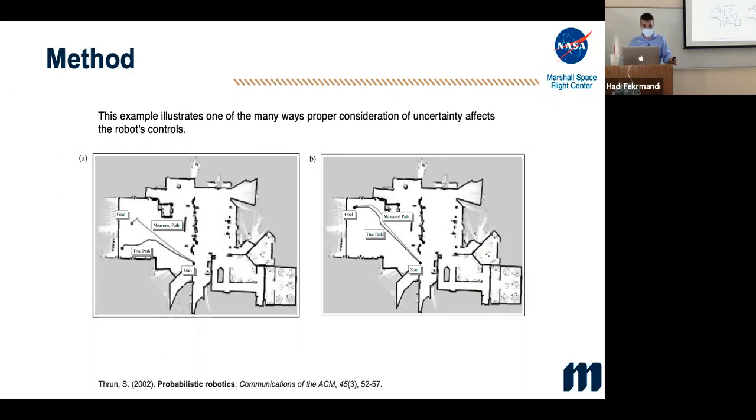In the right image, part B, you can see two trajectories: one is the actual trajectory and the second is the perception of the robot, where I think I am. How do you know where you are if you are only measuring your wheel rotation? That's odometry, or dead reckoning. If you are making estimation with some features, and the trajectory on the right-hand side is close to these features in the environment, then the error is okay.